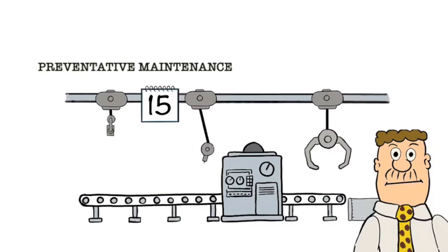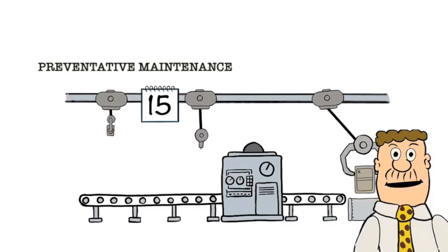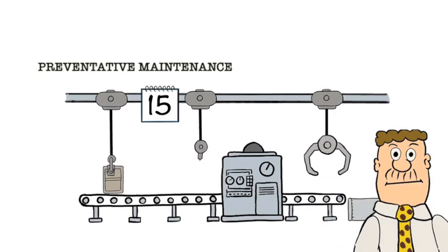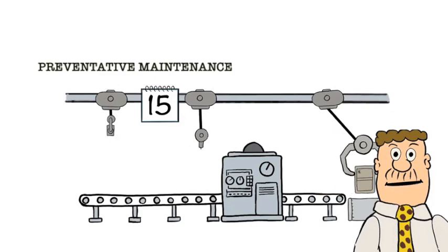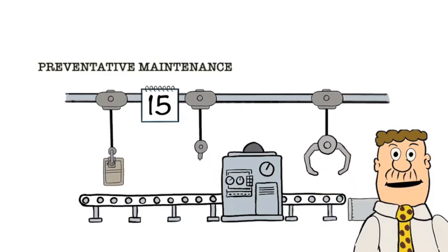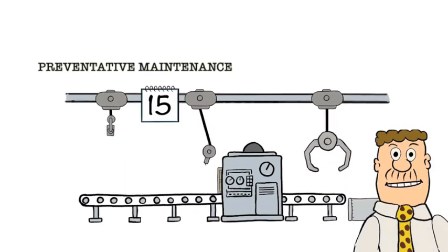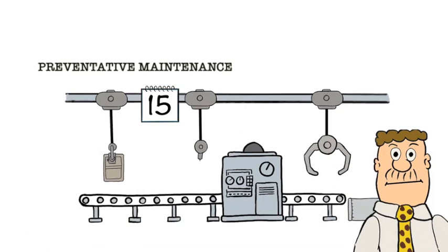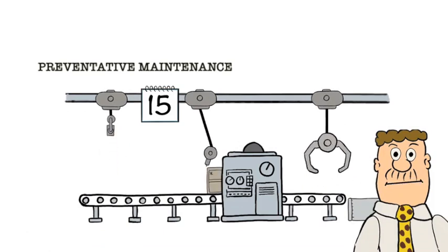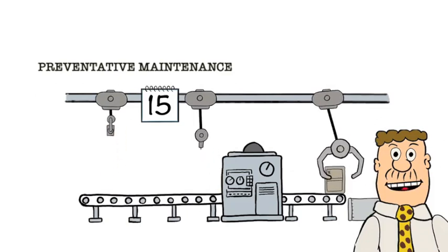In this way, the maintenance can be performed when it is convenient to me, within a tolerance, and sometimes can be done whilst the machine is operating. The downside of this strategy is twofold. Firstly, you may be performing maintenance more often than is necessary, plus the fact that the maintenance itself may cause issues. Often things have gone wrong with my car after it has been serviced. The service itself has made the equipment slightly more susceptible to problems.